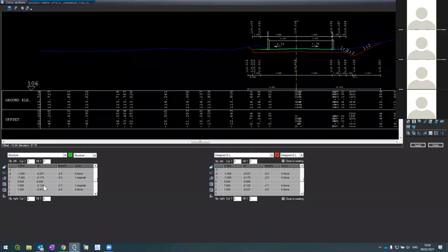Look at the structure here. This is what the software suggested. I'm here on the lower left. In this section, which is in the middle of the super elevation, the right lane changed to minus 1.7. It's still on the side, but starts super elevating. I can change it.